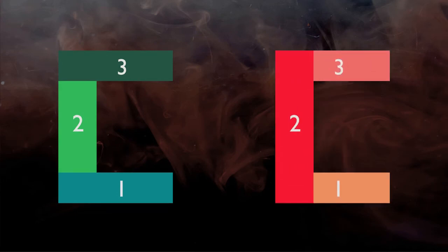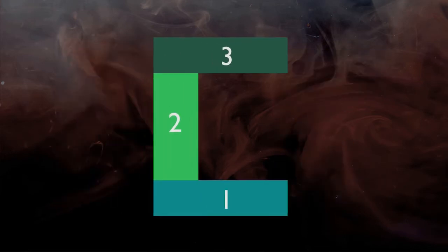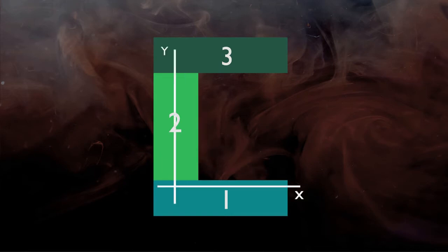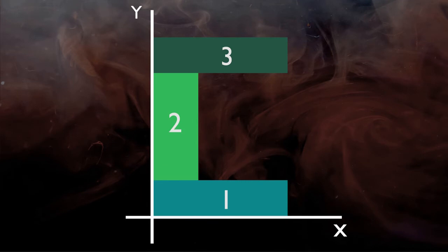You can divide the area as per your convenience, like this or this. Try it yourself for both divisions and you will see that the centroid coordinates are the same in each case. Here we will pick any of these two divisions and find the centroid in the following steps. Generally, try to divide the shape so that at least one axis is touching as many divisions as possible. Like here, the y-axis is touching all divisions 1, 2 and 3. It will make calculations easier.